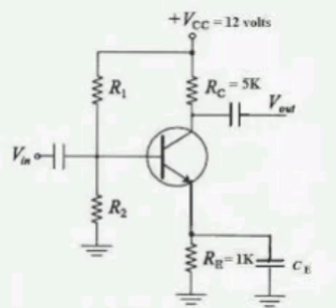Replacing the BJT with the pi model. Vs, 400K in parallel with the r pi model. Next to it, gm V pi current source going to earth, in series with R equivalent equal to 0.86 kilo ohms. Av equal to Vout by Vs equal to minus gm V pi into R equivalent by V pi, that equal to minus gm1 into R equivalent equal to minus 93 into 0.86 that equal to minus 80.